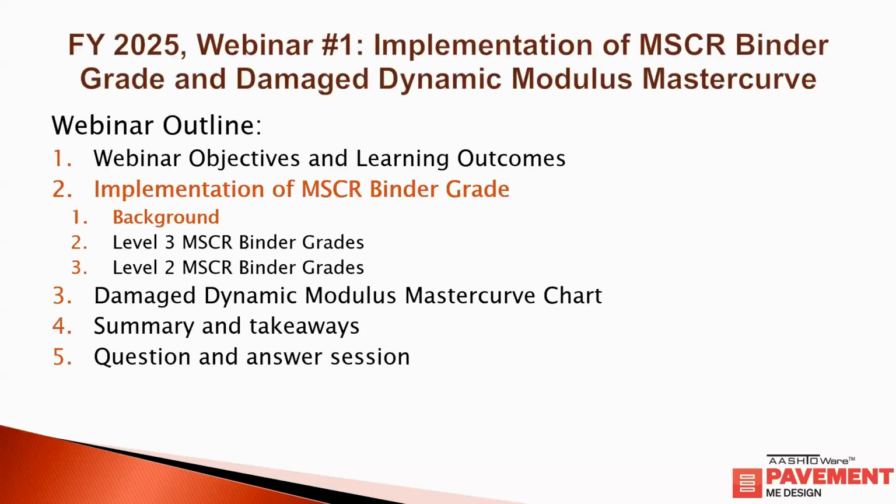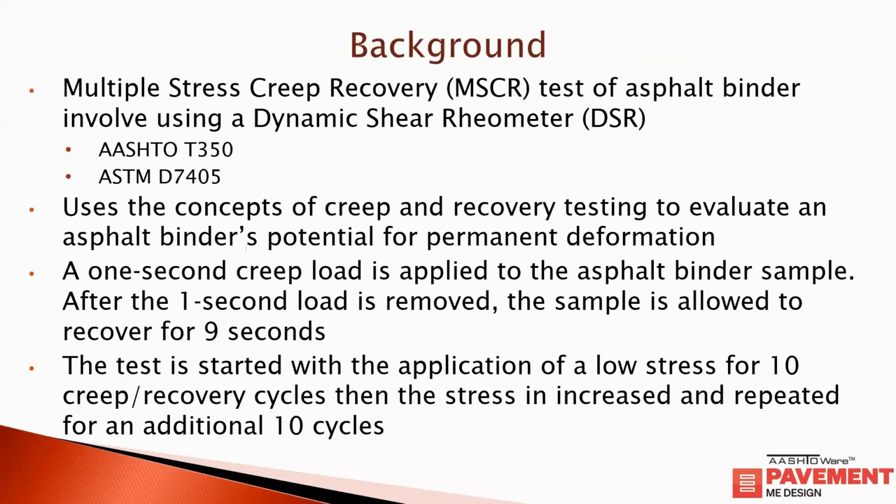Okay, with that, I'll turn it over to Abu, and he will go over the implementation of the MSCR binder grade. Abu? Yeah, thank you so much, Wouter. As Wouter mentioned, the focus of today's webinar is going to be the implementation of MSCR binder grades and initial damage dynamic modulus master curve. I'll be talking about how we integrated the MSCR binder grade into the AASHTOWare Pavement ME Design software. You can see a little bit of background in this slide, and then I will discuss level 3 MSCR and then level 2 MSCR.